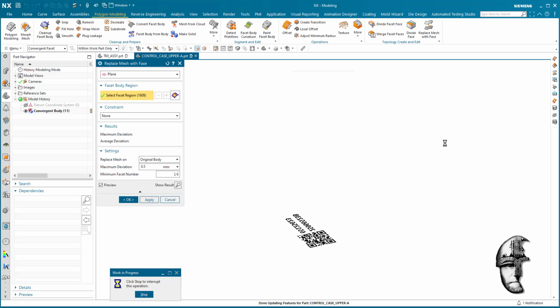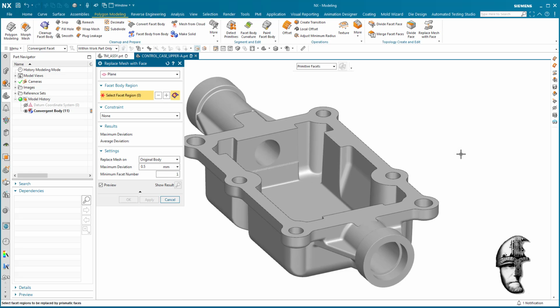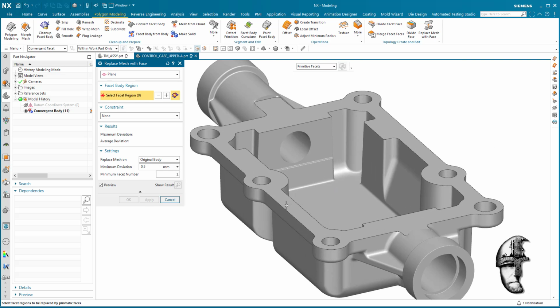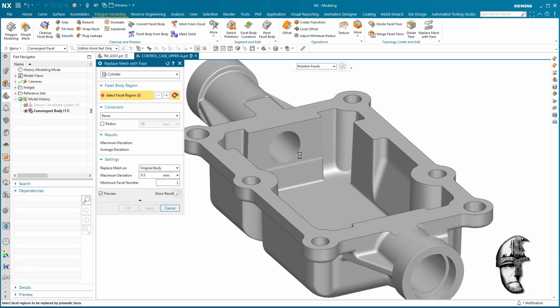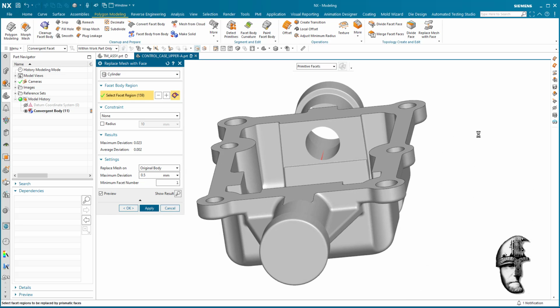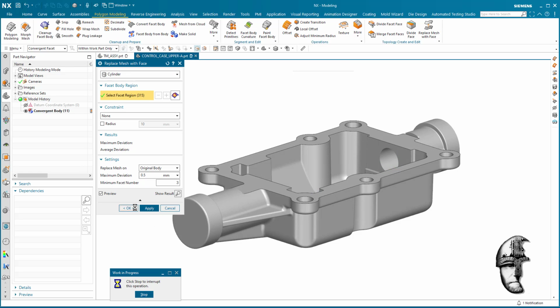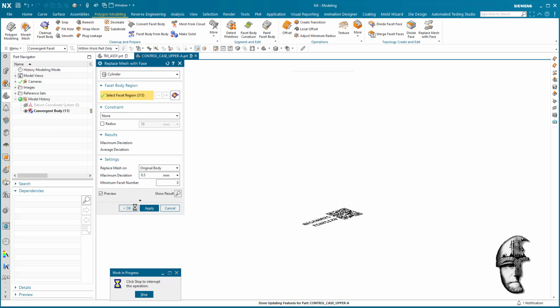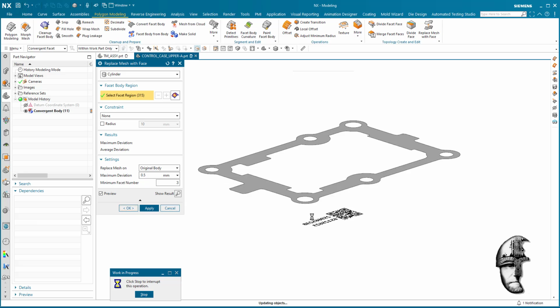it's going to take a little bit of time because it's very heavy on facets here, meaning we have a large amount of them, and we're going to change the shading here. We're going to add edges so we can see the edges of the faces, and we can see we now have a black outline there of that face, meaning that we have an edge there. But we're not done yet. We need to separate the cylindrical faces here as well to get the proper inside and outside, and that should be fine, and I'm going to be happy with that, because we could also create a planar face for the bottom here, but I don't really see the point there.